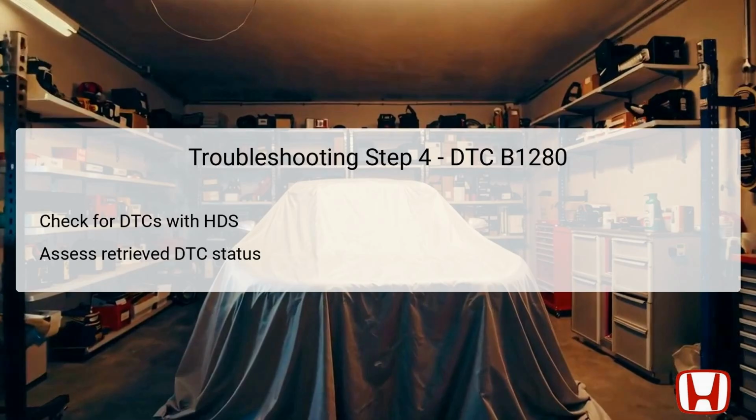If the DTC B1280 is indicated again, it suggests that the issue remains unresolved. Conversely, if the code does not appear, it may indicate an intermittent failure, suggesting that the system is functioning correctly at that moment. However, you should still investigate potential causes like loose or poor connections, as intermittent issues can commonly signal underlying problems that need addressing.